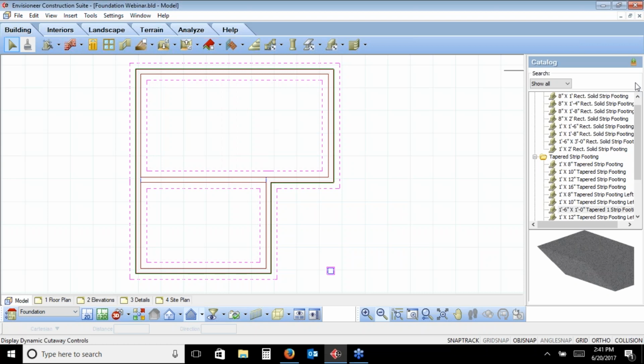So if we're looking at this, I'm just going to pull this into a 3D view. If our lot out the back of the house here is the terrain level, and I'm just going to slope it down so we've got a good illustration here of -8 feet. If it goes down 8 feet and you've got a walkout basement, how do you manipulate the walls and the footings to handle that so that you can step them down in that situation?